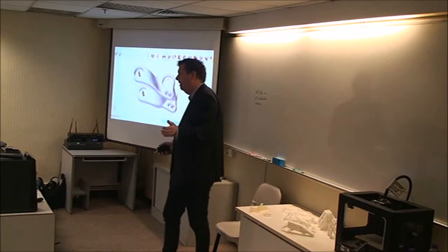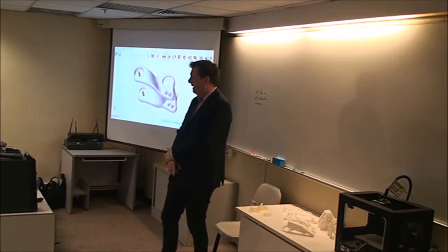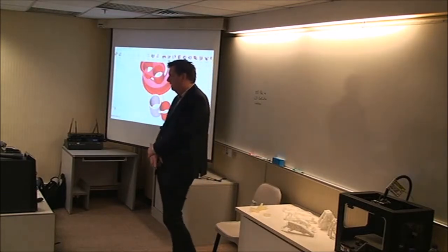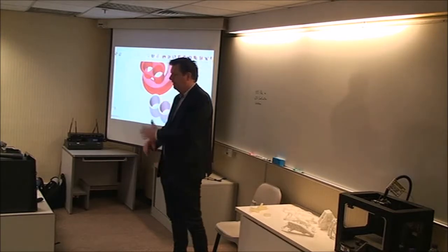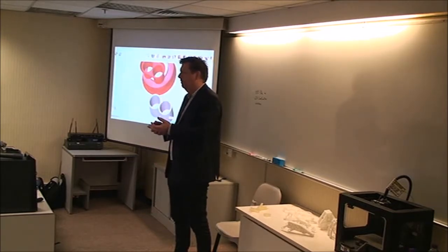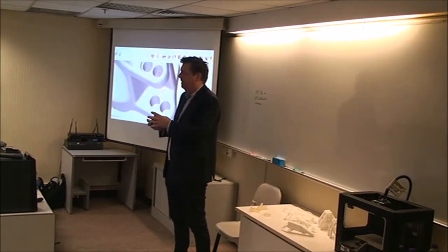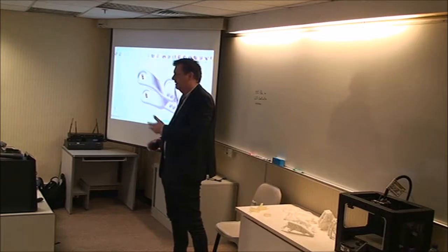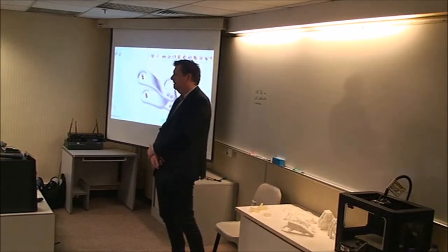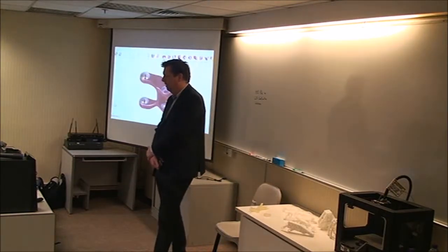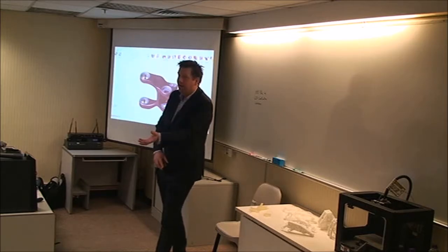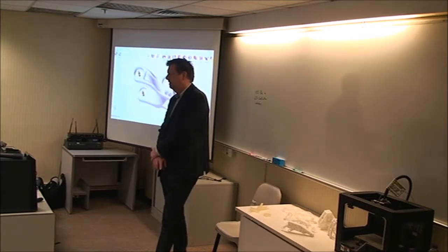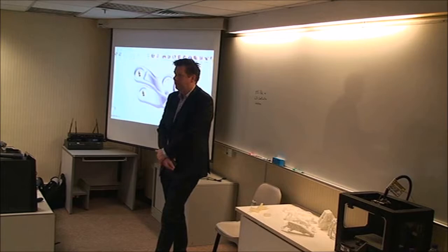You want to get rid of them. You want to back off to get more of the package space. These are partition tools. So again, when people do CAD, you're not normally dividing a part up into where my loads are going to be, where my supports are going to be. You just have a part. So we've got various tools in Inspire to help you break the model up. So now you've got these grey non-design regions with your loads and supports, and then the designable region.